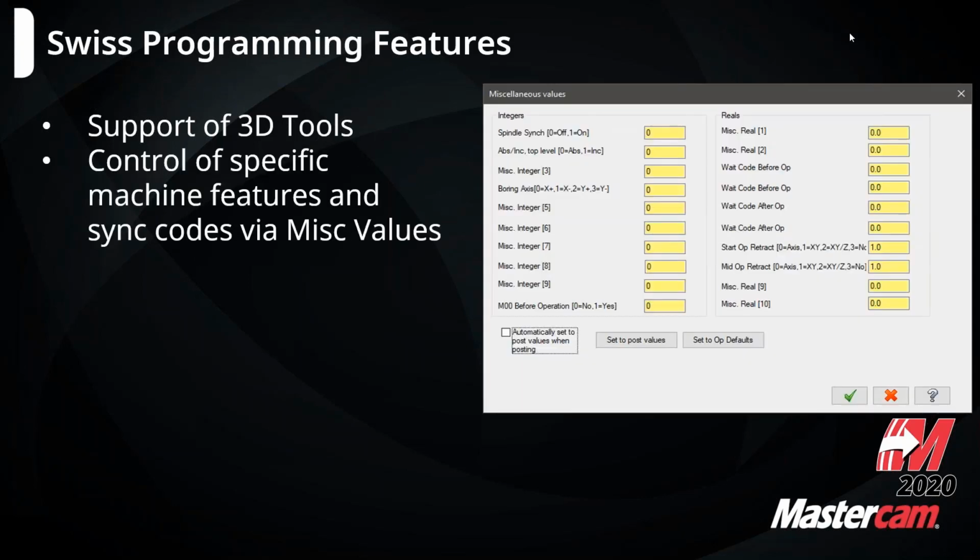Next is controlling specific machine features via miscellaneous values. If any of you haven't been in this screen before, it's typically on the first tab of any toolpath on the lathe side of Mastercam, and a little farther down on any of the mill or live tool toolpaths. We can have stuff built in here already, and also add stuff based on customer feedback to this section. A lot of these Swiss posts will come default with a screen like this, where you can insert wait codes before or after the op and control some spindle syncing and some other specific features depending on the particular Swiss machine.